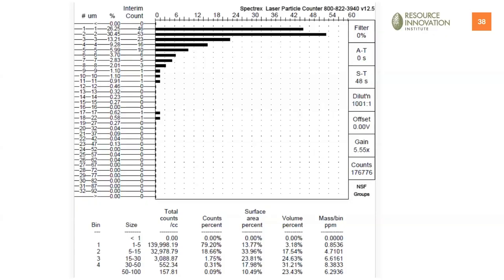You can see here there are many small particles up at the top, from 1 to 5 micron in size. And then you'll see there's another blip somewhere around the 15 to 40 micron size particle. And it doesn't look like there's many, but if you look at the table on the bottom, it's a little bit cut off, but there's a high volume percent and a high weight percent from those larger particles. And if you don't design a coarse filtration to take care of those, they'll foul your fine filtration filter, and you'll spend a lot of time cleaning that filter. Next slide.